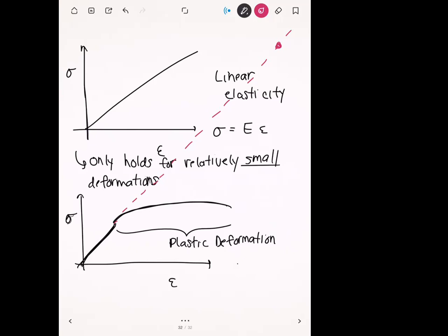Professor? So I know you said that we want to start looking for plastic deformation at larger deformations. Is there a numerical way to do that? Say, for example, your material is like 6061. You look up your stress strain chart, find out where the chart turns from linear deformation to plastic, and then run a simulation without plasticity. You look at the highest stress. If that highest stress is above that turning point, would it be a good idea to turn on plastic deformation? Yeah, I'd say so.